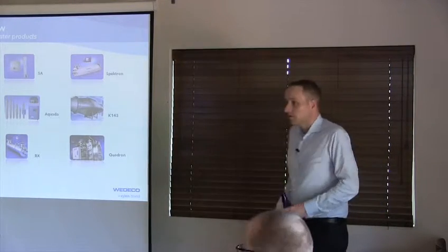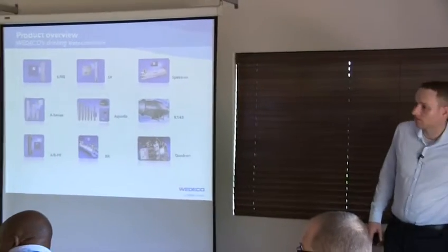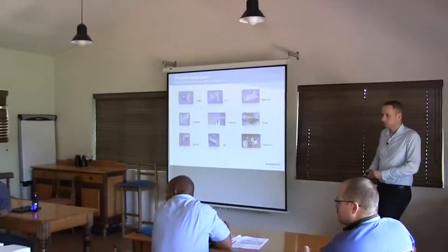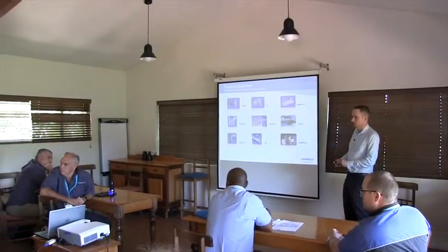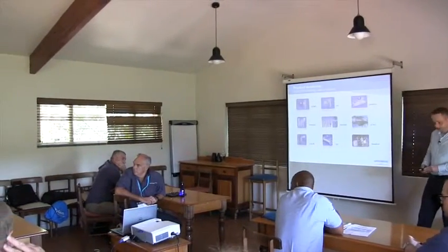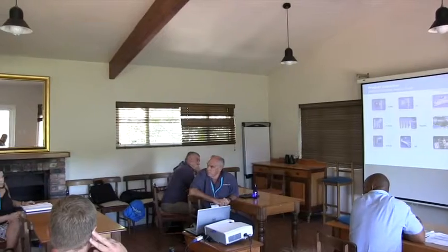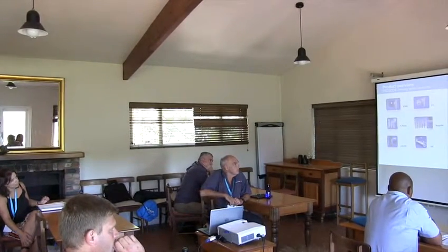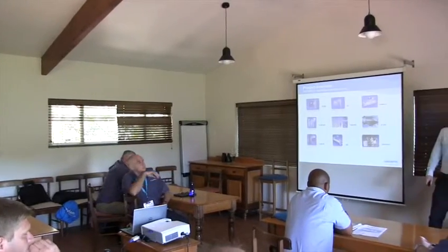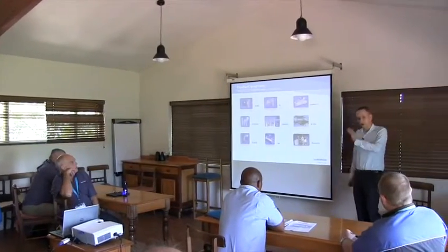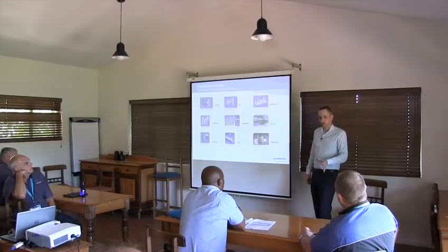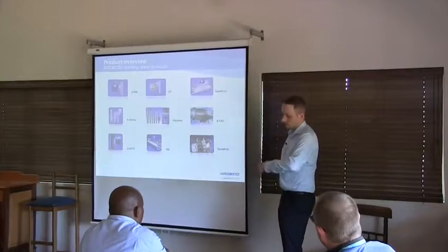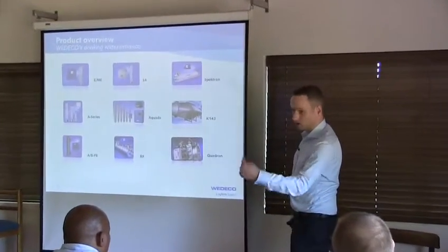So just to clarify on the UVT, that's the measure of the UV light that is being transmitted through the water. If it's 80%, the higher your UVT, the better the quality of the water. It's normally measured in 1 centimeter. So if it's an 80% UVT and you put 100 watts of UVC output inside the water, then after 1 centimeter you still have 80 watts. But after 2 centimeters you only have 80% of 80 watts.